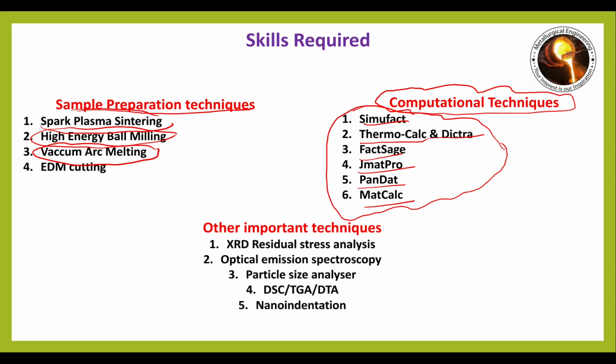There are some other important techniques. For residual stress analysis we have XRD, which is a non-destructive test. We have a destructive test also, like hole drilling. Then we have optical emission spectroscopy for composition analysis, spectroscopy, particle size analyzer, and DSC, TGA, DTA. These are very useful: if some kind of phase transformation is happening in a sample, we can determine the exact temperature at which the phase transforms from one phase to another.